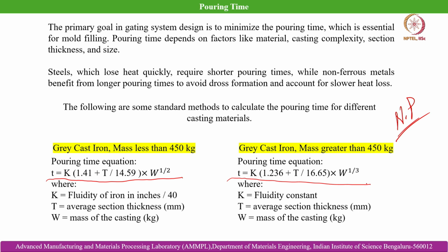These are empirical relations developed for industrial practice, so that the pouring time can be estimated in a short span of time, along with the other process conditions and the gating geometry. This also helps predict the microstructure and the cooling rate that the solidifying melt will be subjected to. All these estimations can be done based on the estimated pouring time.